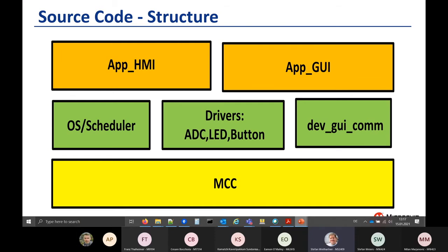They are connected to the timing of the scheduler, so the LED can blink, and you have very nice interface functions for slow blinking, fast blinking. Also, the button driver has nice features for getting information if the button is pressed longer, and has a debouncing algorithm inside and so on.